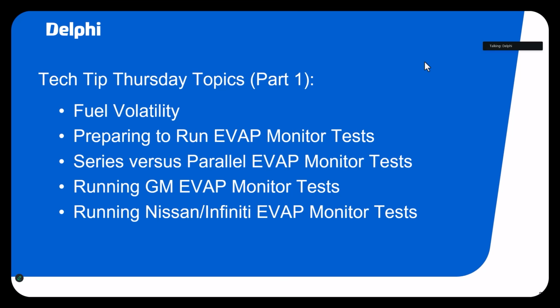I hear constantly that they don't run, and that people don't worry about them because they're not required for a typical state inspection. There are some states, though, that if you fail for EVAP, then that monitor test must be complete and that flag must be flipped for EVAP to pass an OIS test or a state inspection test.